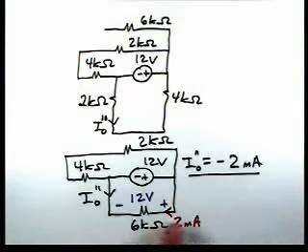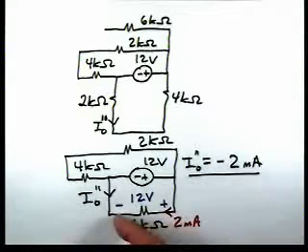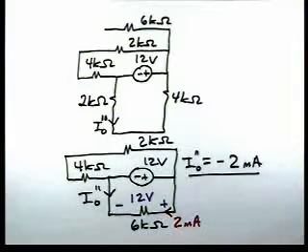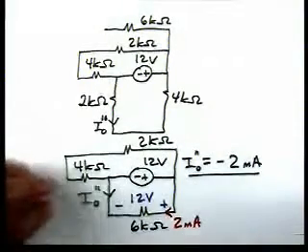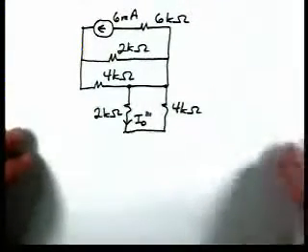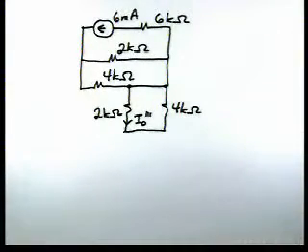So here, by Kirchhoff's voltage law, this had to be plus and minus. By Ohm's law, we know the current has to be flowing in this direction, 2 milliamps. I0 double prime is defined in the opposite direction. So we have one remaining source. That's the 6 milliamp current source on the top.